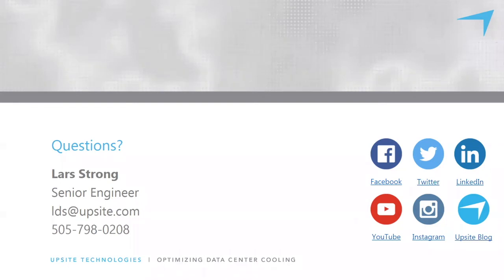Thanks, Lars. We have another one here related to PUE, and it's not much of a question, but I think it adds to what you were just saying. PUE could be a live parameter. It's often quoted as a seasonal or annual number. Real-time analysis utilizing all air data halls has some very low PUE values with low outside air temperature.